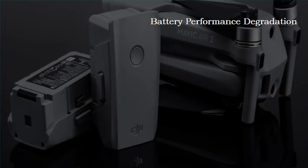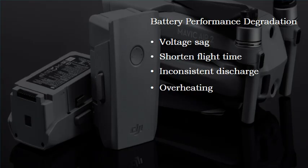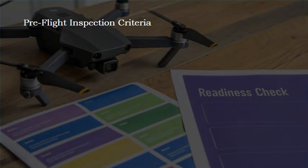As a drone owner, you must look for the signs of battery performance degradation. Some indicators include voltage sag, shortened flight times, inconsistent discharge curves, and overheating during charge. One way to ensure a drone is ready for load and performance challenges is by conducting pre-flight performance checks. A comprehensive sUAS pre-flight check ensures safety and legality by verifying the environment, aircraft, and controller.